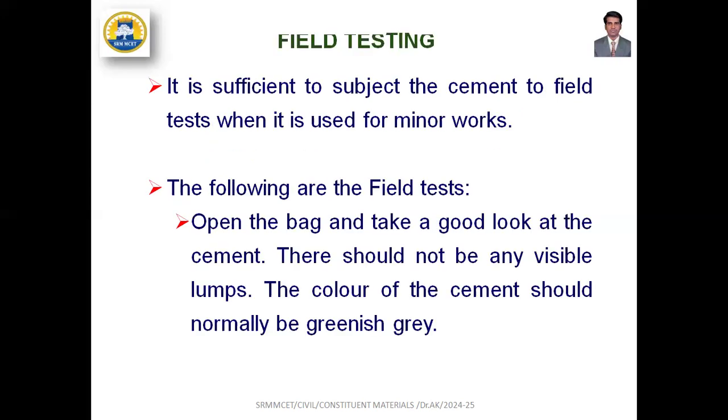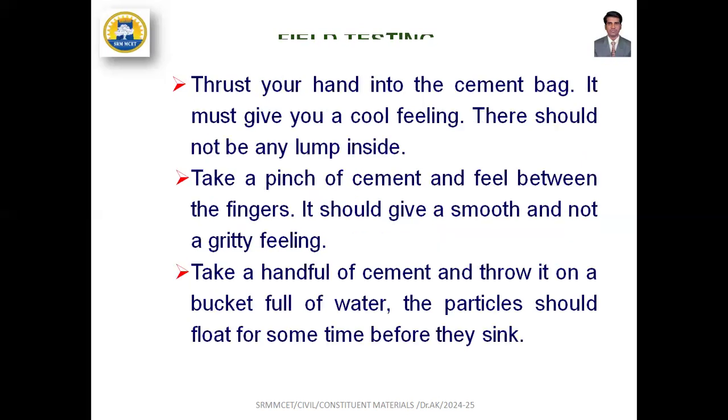In normal field testing, you open the bag and the color of the cement should be greenish gray. Take a pinch of cement in your hand; it should be free from lumps and you should feel a smooth texture. If you put a pinch of cement in a bucket of water, it should float for some time before it sinks. If it satisfies the above criteria, we can conclude that the cement is of good quality.